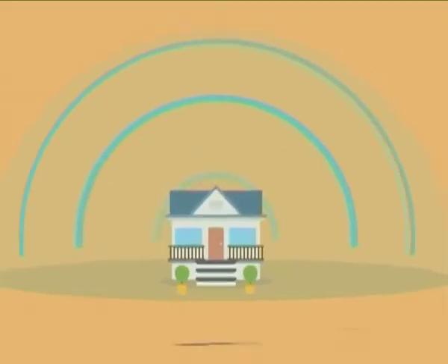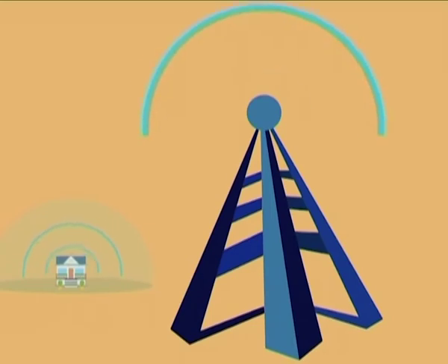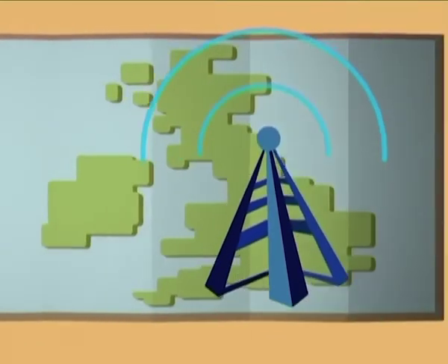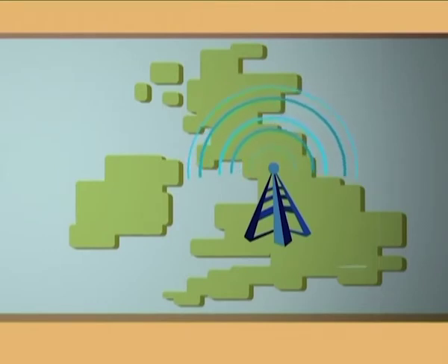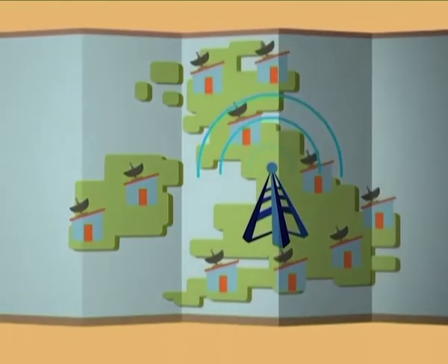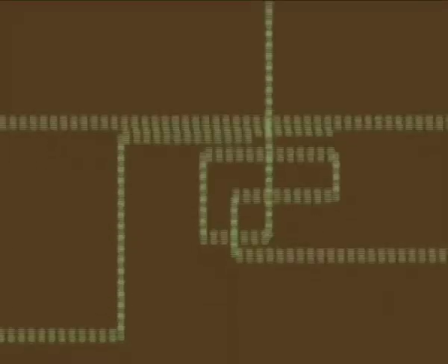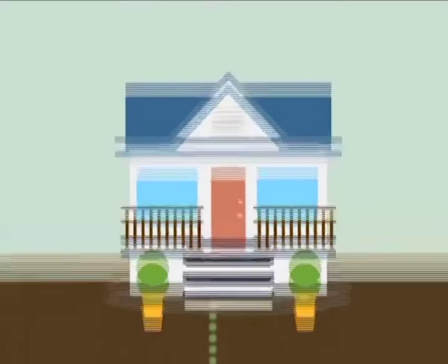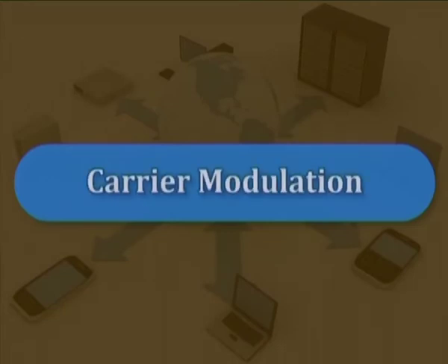Wireless LANs use electromagnetic waves to communicate information from one point to another without relying on a wired connection. Radio waves are often referred to as radio carriers because they simply perform the function of delivering energy to a remote receiver. The data being transmitted are superimposed on the radio carrier so that they can be extracted accurately at the receiving end. This process is generally referred to as carrier modulation.